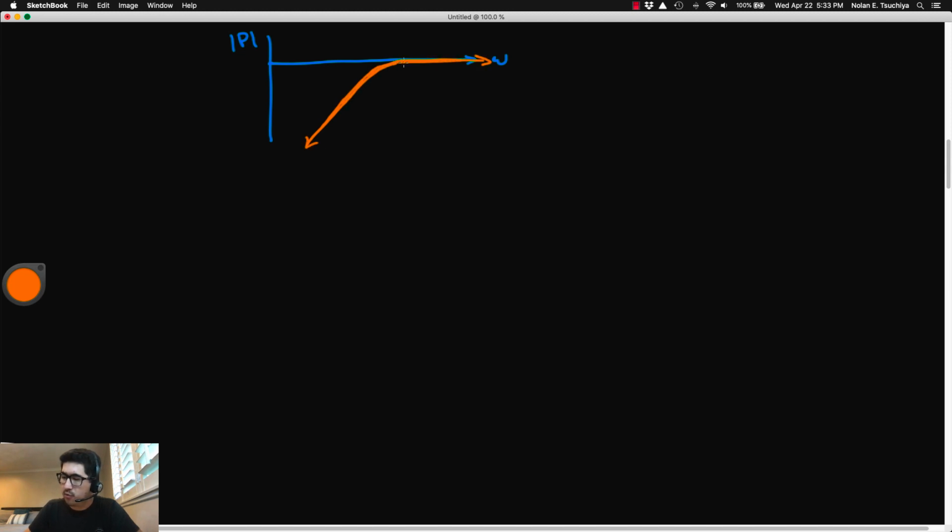through, right? If we're speaking in terms of, say, an audio system, if you're building a nice fancy audio system, you don't want to send your entire music file or whatever music you're streaming, you don't want to send that entire signal through, say, a tiny tweeter speaker. If you just have a little tiny speaker which is only capable of reproducing really high frequencies, then you don't want to attempt to pass a bunch of low frequency content through because it simply can't produce that range of frequencies. So before your source audio reaches a tiny tweeter speaker, you may want to pass it through a high pass filter so that you're really squashing down all those low frequencies and you're only allowing those high frequencies to pass through.